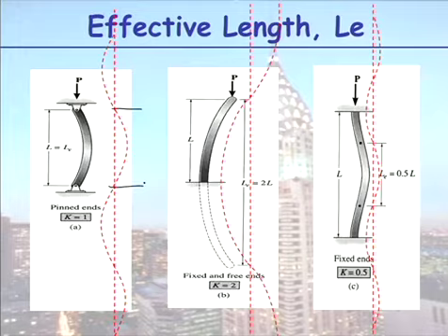However, I'll do this case here. You're now grabbing it top and bottom, and watch the way it buckles. The way it now moves is, remember, at a fixed support, there's no rotation at the fixed supports. So can you see when you think of your half sine curve, the effective length for your half sine curve is now half the length.